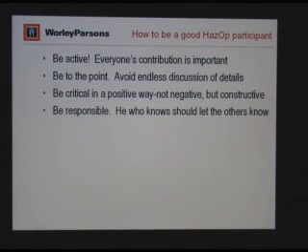It may not be a problem for the process people, but the equipment group may think, oh, this will be a problem. And also be to the point and avoid endless discussion of details. In a lot of HAZOPs, where a group of engineers with operators, once they identify a problem, they just keep on going and going and talk about the subject and try to solve the problem.